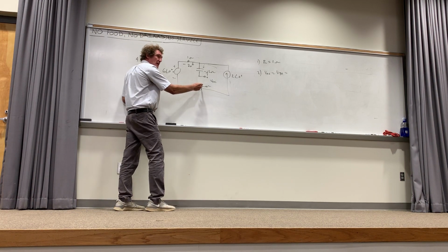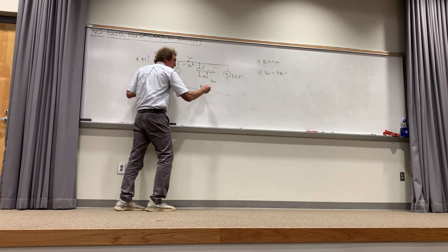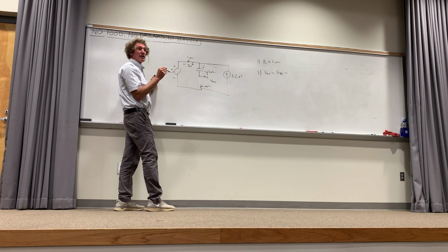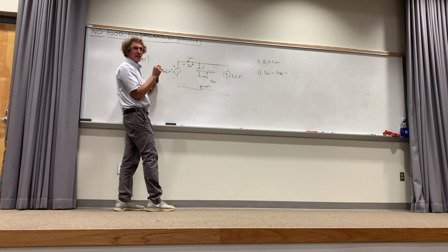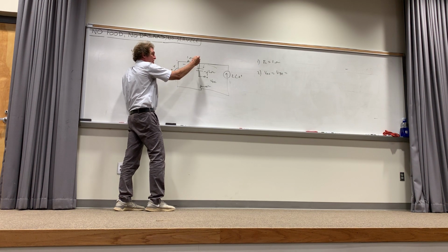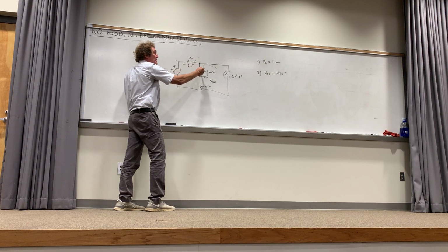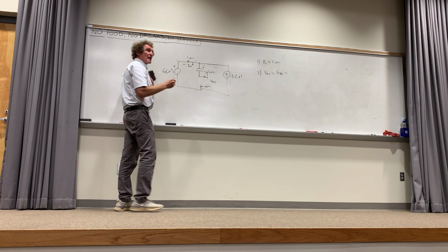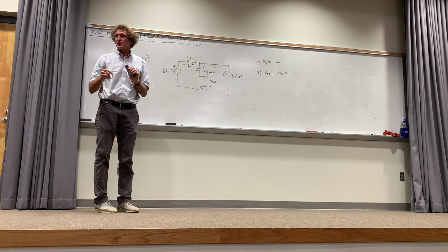So we're ready to figure out the open circuit voltage. We start here. Now, can I go this way, class? Why not? It's a current source. You don't sum voltages through a current source. You don't know what it is. That's a common mistake. You go this way. And when I go this way, what do I see? An increase of 6, and then an increase of 2, and then nothing, right? So we get 8 volts, open circuit voltage. How many see this?